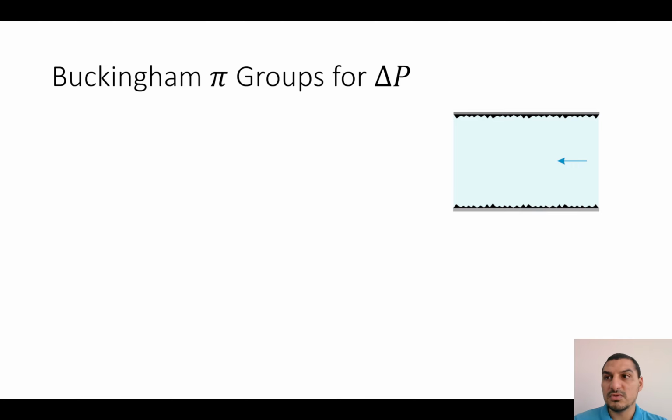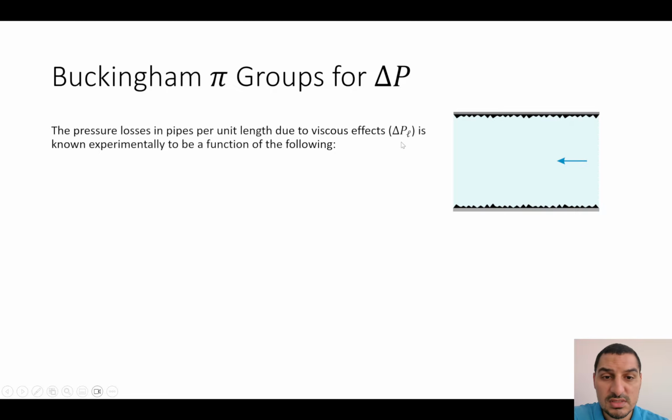So it can be expressed in terms of length, which is HL, or we can express it as pressure drop. Both represent the same thing. So when we have losses, it will be observed in the pressure loss. So now we are going to see how we can create dimensionless groups for this delta PL, which is the pressure losses.